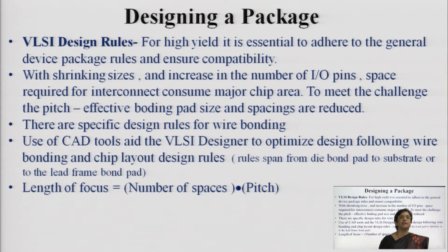With shrinkage in sizes, an increase in the number of input output pins, the space required for the overall chip area is reduced, and to meet the challenges, the pitch, which is the separation between two devices, and the effective bonding pad size are also reduced, and there are specific design rules followed for wire bonding.